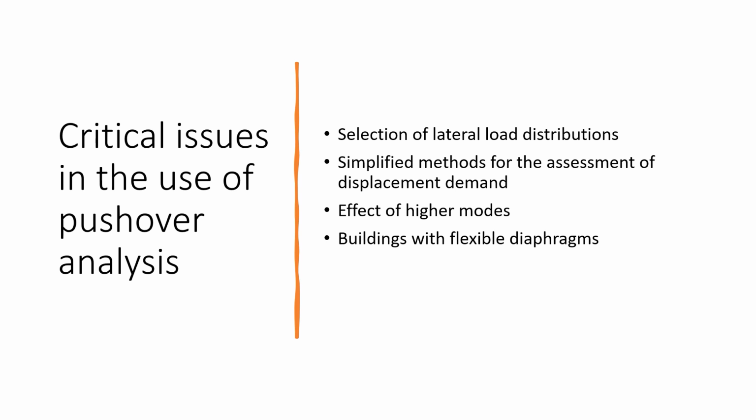And this is because the dynamic response of the different parts of the building is no more effectively coupled by the presence of a stiff diaphragm. And this is something that makes pushover analysis not easy at all in that case.